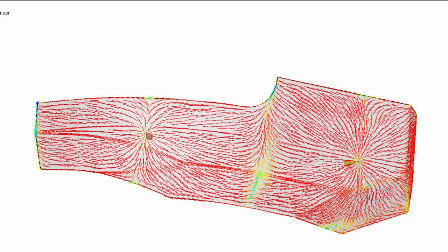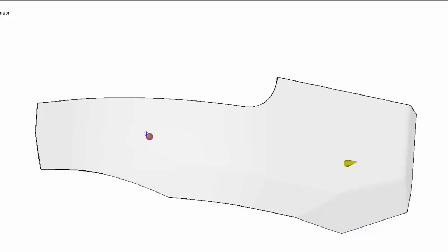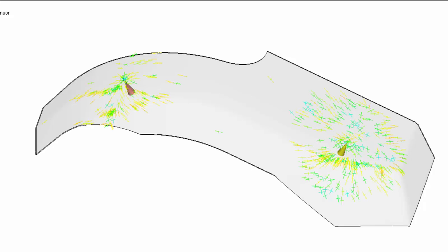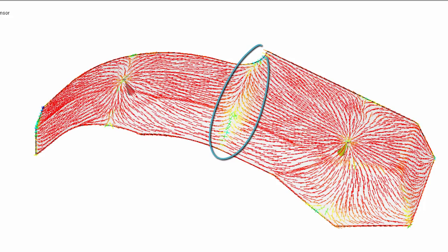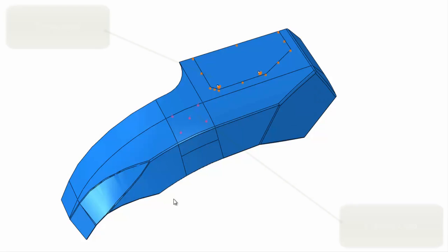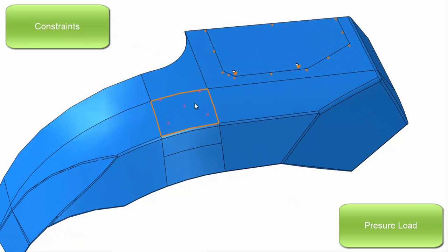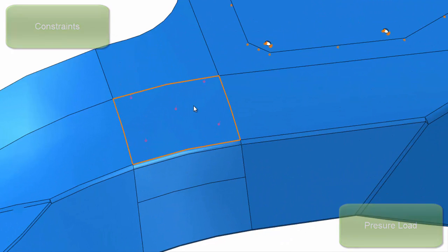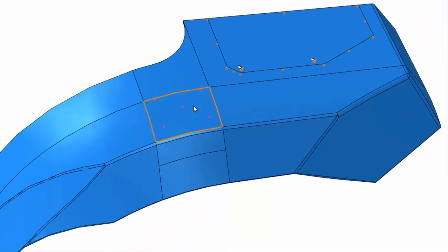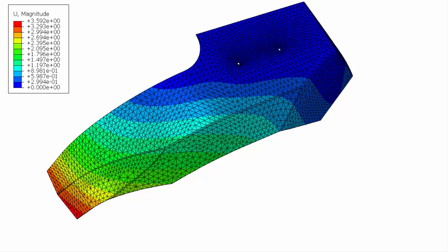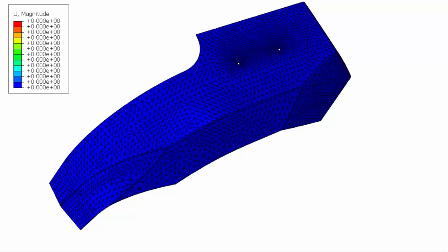For fiber-filled materials, fiber orientation causes orthotropic behavior of the material, which in turn changes the stiffness of the structure. Weak areas of the structure are created where two flow fronts meet, which are known as weld lines. Residual stresses and strains can contribute to a deformed shape and a pre-stressed material prior to mechanical loading. Using as-manufactured properties within the structural simulation can only increase the accuracy of the simulation and help to identify potential areas of concern before the part is manufactured.